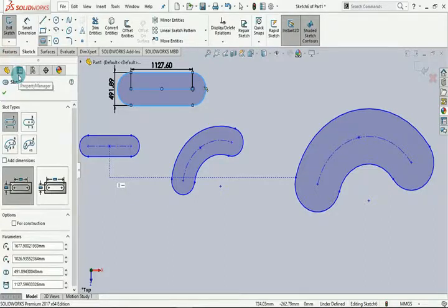And also you use slots if you are doing mating between two parts, and then you want to create kind of tolerance with them so that one can be fixed and the other can still be adjusted. So you definitely need to use your slots. So rather than creating two circles, joining them with two lines, and then looking for how to cut in between those lines, we just go straight to the point and use the slot tool.